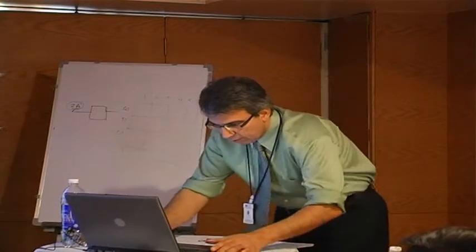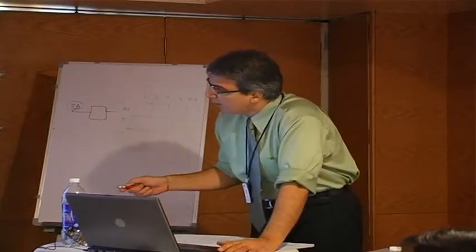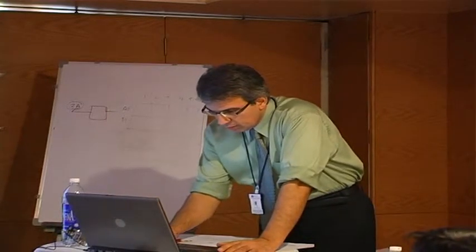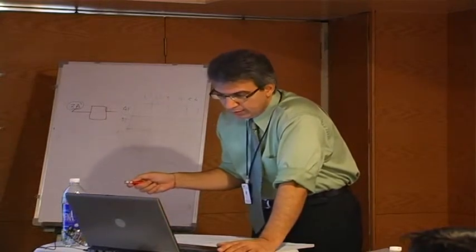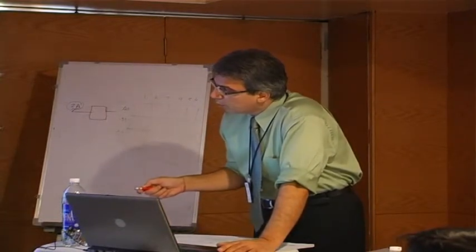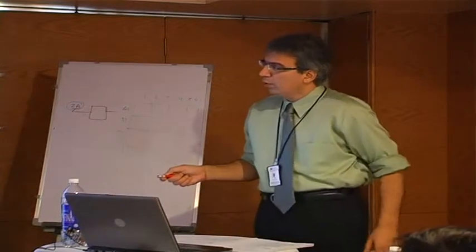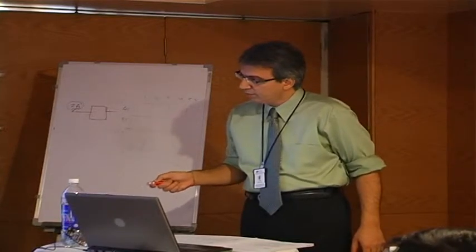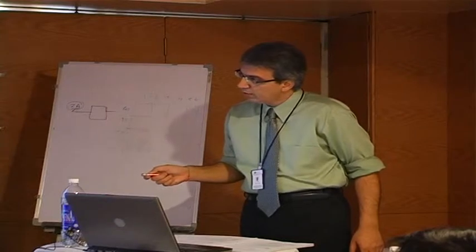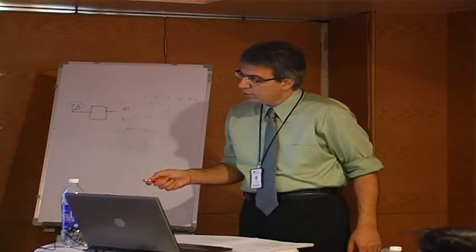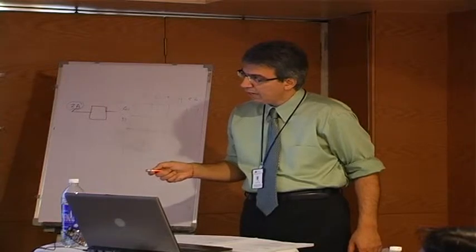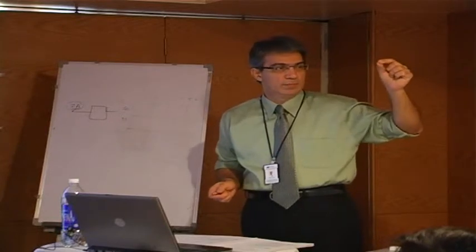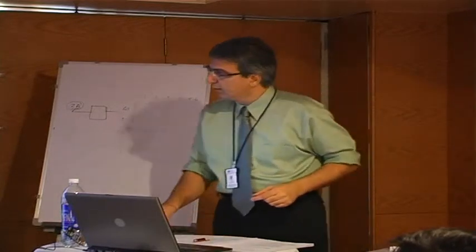Let me just verify one thing here. So you have similar delays: delay 1, delay 2, delay 3, delay 4, delay 5, delay 6. I want to explain this particular function here. We take this waveform, which goes plus and minus. Now by using this function here, we are able to generate I reference A, which is now a duty cycle command, and this goes from 0 to 1. So what we have done is normalized.